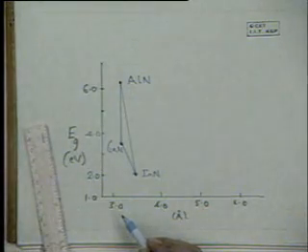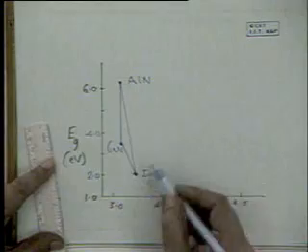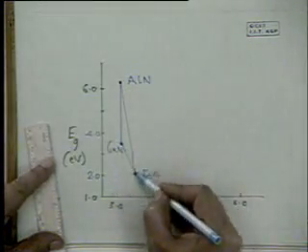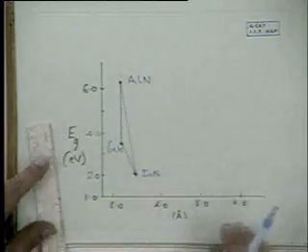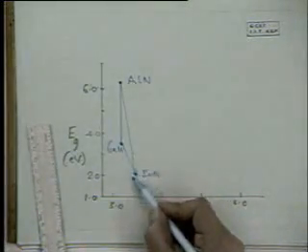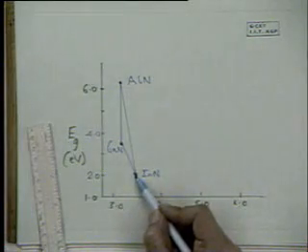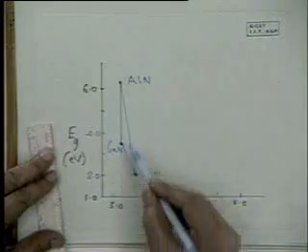And these are all direct gap materials, so you can get solid solutions of indium gallium. But obviously here you have lattice mismatch problems. Aluminum nitride, indium nitride and gallium nitride have slightly different lattice parameters, but you can span the entire range from 2 to 6 eV.